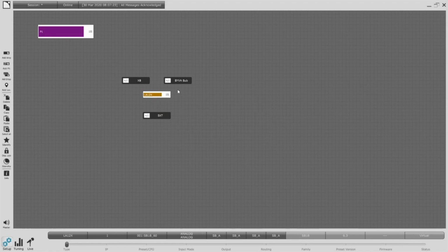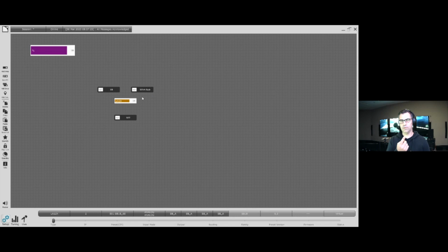We use a group for anything we want to mute, gain, delay, change the polarity, or EQ. We're also going to use groups for anything we might want to measure. If we want to take a measurement of a specific part of our sound system, it needs to have its own discrete group. We can also have additional groups, for instance, a parent group for something like the all or maybe the mains.